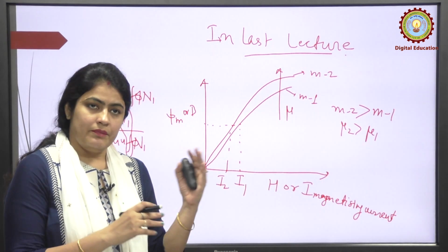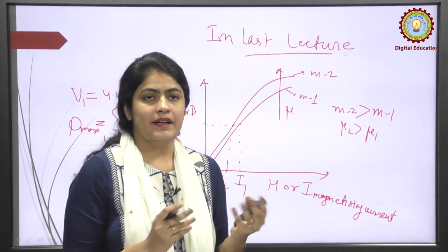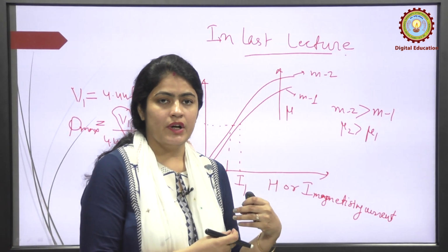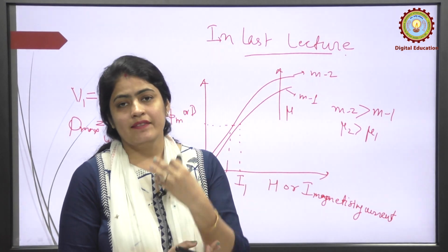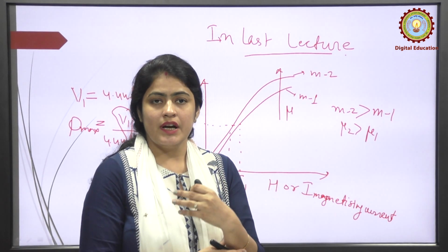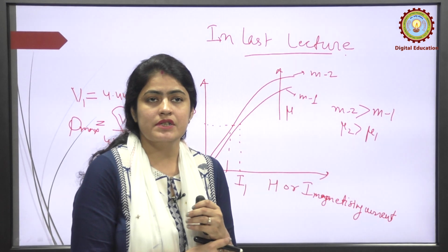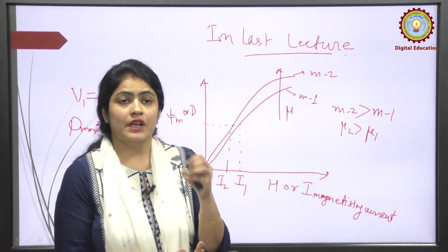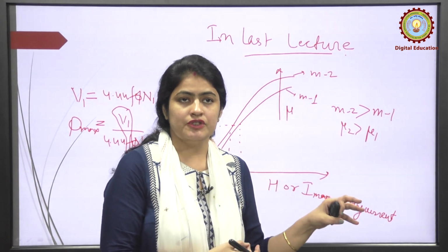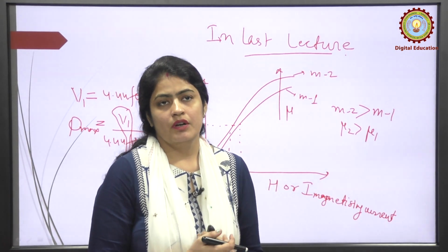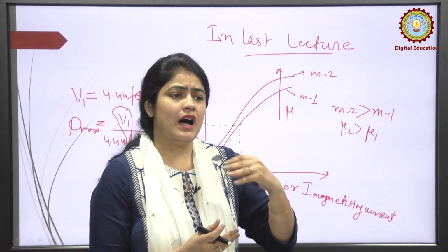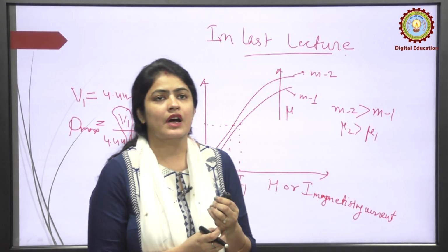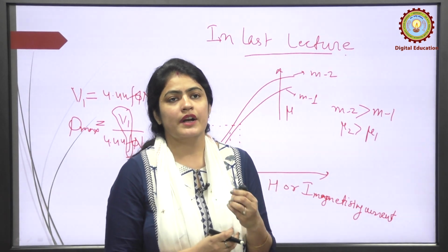So, this is the concept we discussed about the magnetizing current and how it comes into the picture. When you apply the voltage, flux is produced, and that flux is constant; it depends upon the voltage and the frequency. The current required to produce that much flux is very small, and if you take a better material, the requirement of current becomes smaller and smaller.